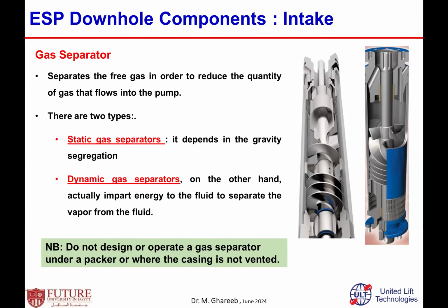There is a rule of thumb when you start to design ESP pumps, depending on the type of pumps, type of stage, and so on. If there is free gas at the pump intake above a certain value, then you have to use a downhole gas separator. You don't need to design or operate a gas separator under the packer. If there is a packer above the pump, then you don't need this downhole gas separator.